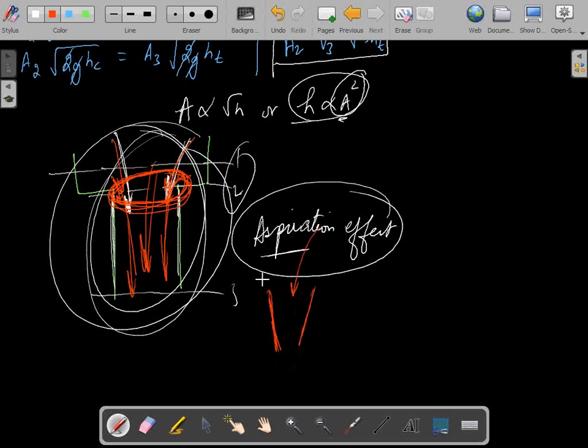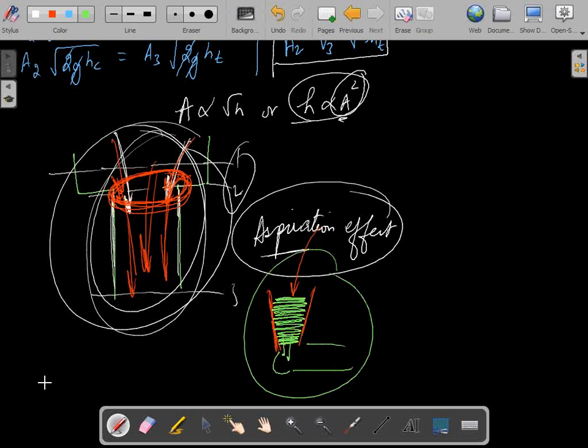When you pour in the liquid, it will start filling up like this, and it will push out any air from it. Then slowly it will trickle down into the sprue well and then onto the runner. So this is the practical thing: with the tapering section the flow rate is also controlled, and with a cylindrical section it falls freely, creating a negative pressure head at section 2, which is called an aspiration effect. Understood or no?